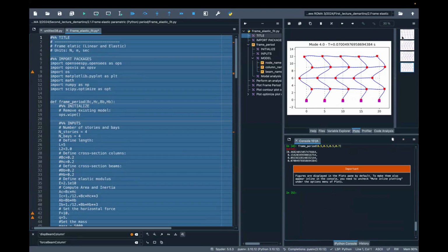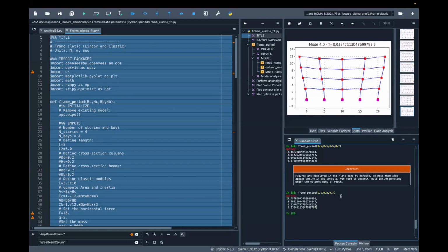Anyway, you can see here that we have the period. Obviously, we can change it. So let's see, you can check if your model makes sense, okay? This is what we call the parametric investigation, right? So if I change my columns to be 1, 1, what is your expectation? My expectation is that obviously the mode shapes are changing too. I made the columns quite big. My expectation is that the structure is much, much stiffer, right? And then the period is going down.